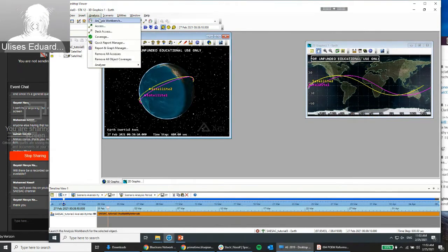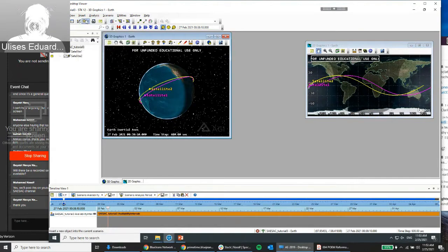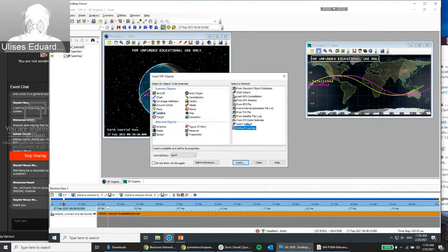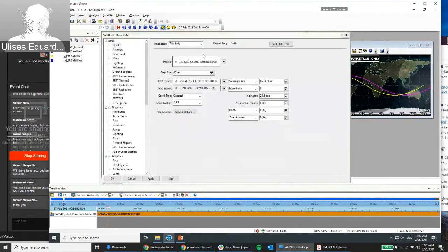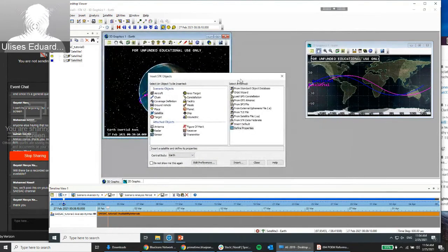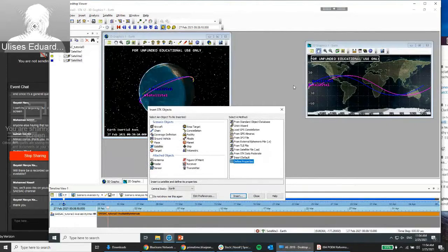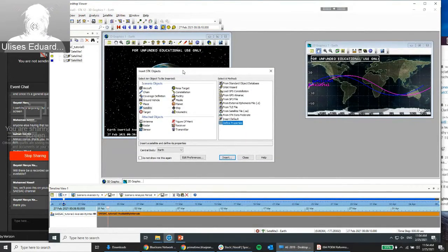All right, so now say that we create yet a different satellite. Let's say that this one is going to have J4 perturbation. In this case, we're accounting for up to the fourth oblateness term. And see, that one and J2 are actually kind of similar. They're almost right there on top of each other. So J2 is a really significant term.